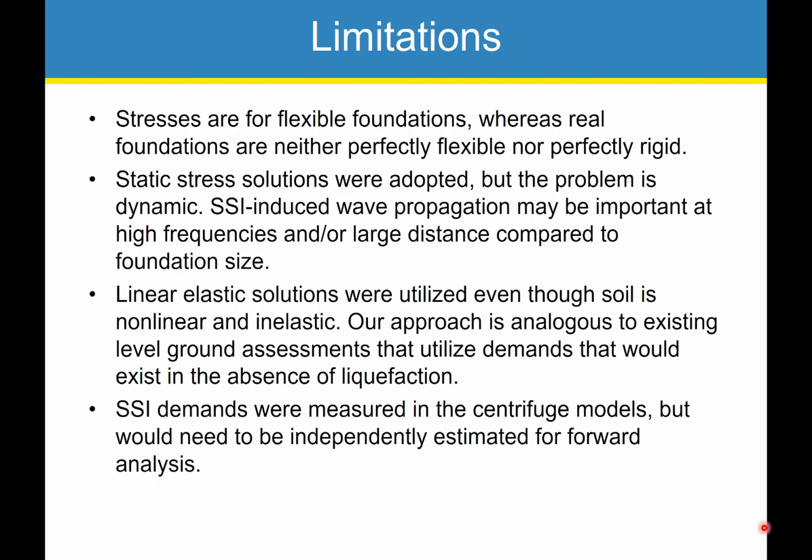We use static stress solutions, but the real problem is dynamic. SSI-induced wave propagation might be important at high frequencies. So we used ground motions that are from pretty active tectonic regions. Ground motions in stable continental regions tend to have higher frequency content. That might be an issue. Also, if you're looking at a large distance away from the footing, there's more opportunity for that wave field to form and be out of phase with the free field ground motion propagation.